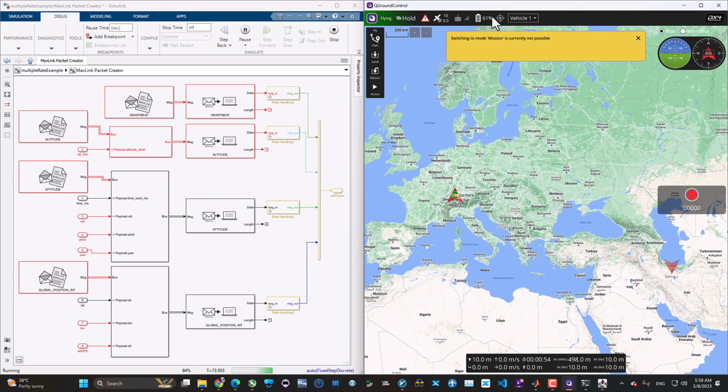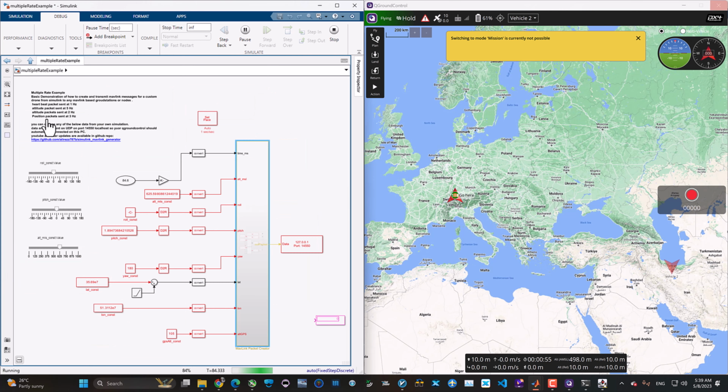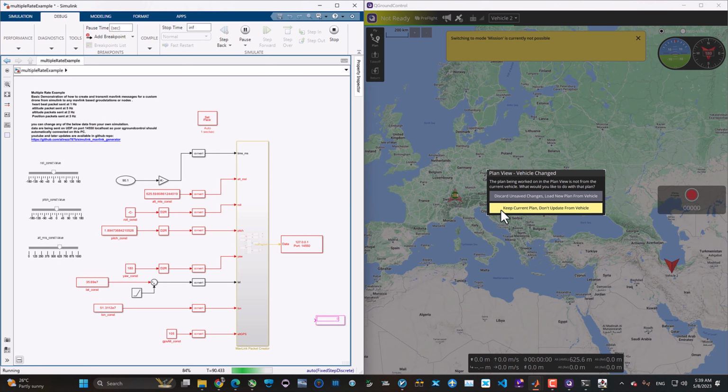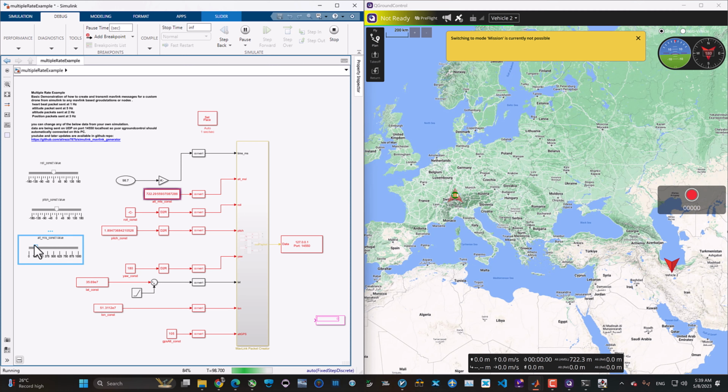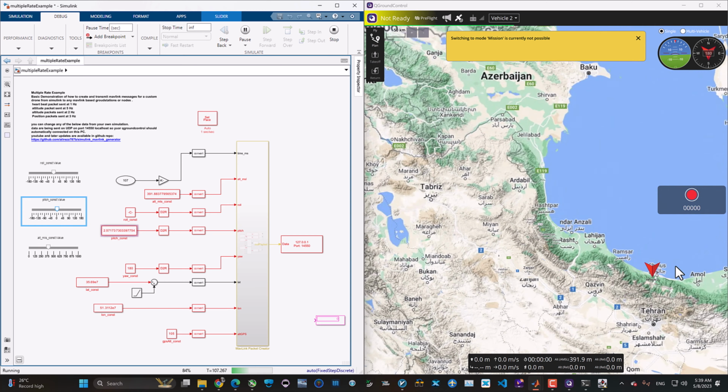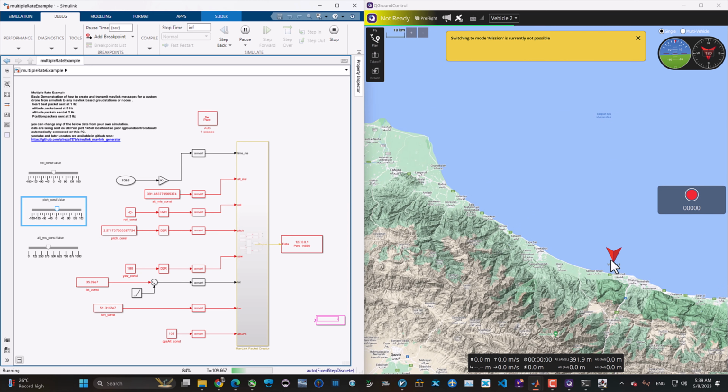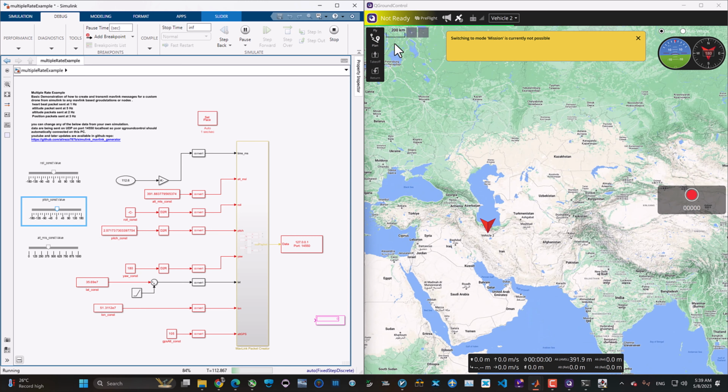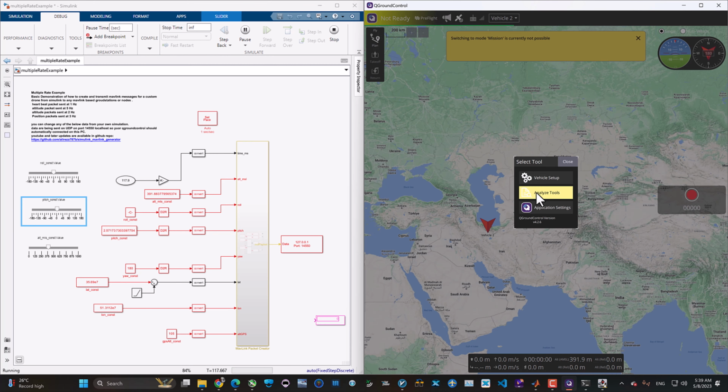We can switch to the other drone here, vehicle 2, which is our virtual Simulink model of a drone here, and then we are focusing on vehicle 2, and we can change the parameter here. For example, if I change the altitude here, you can see the vehicle 2 altitude would change. The altitude is changing. You can change the pitch, roll, and meanwhile vehicle 1 is hovering somewhere around Zurich. This is a very fun project. You can coordinate drones. If you are involved in a drone show or swarm project, you will find many vehicles here you can manage at the same time.